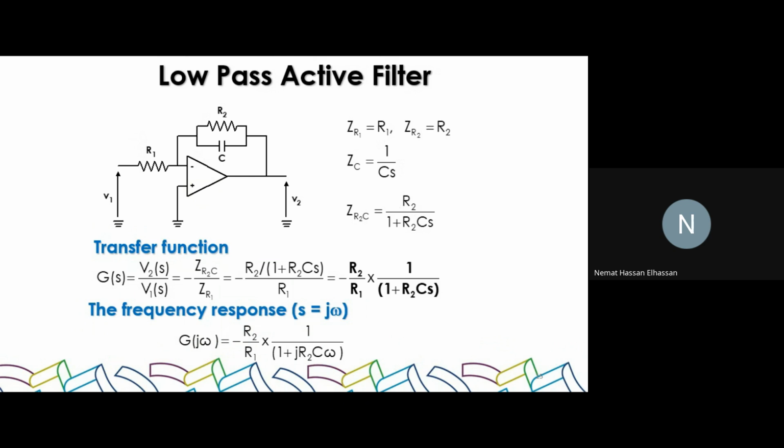Now, keep in mind that right now I'm just looking at simple basic circuits, but when you scale it up, it becomes more complicated. The reduction will be even more significant. But if you look here, I used a lesser number of components, but it will be the exact same output. And the reason is I implemented the filter in the feedback loop. We call the line connecting the output to the input the feedback loop. So instead of having a filter in series with an operational amplifier circuit, I've put the filter inside the circuit as part of the operational amplifier itself.